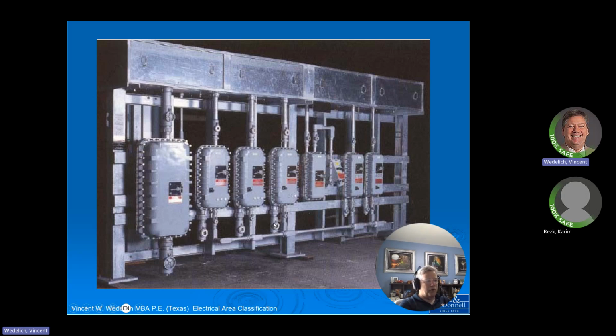It's supposed to be 40% inside there. If you buy a standard seal, it's 25% fill. But if you buy an expanded fill, then you can fill it up at 40%, which happens to be the conduit fill for the NEC, right? Unless it's a multi-conductor cable, one multi-conductor cable, 53% fill, but you can't do that here, right? You have to follow these rules.